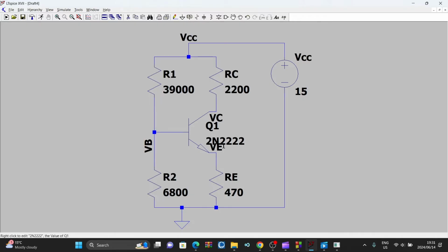Then when you minus, there's a voltage drop here, VCE. So how you can do that is, you can minus VC minus VE. That will give you a voltage drop across there. Yeah. Then this is our circuit for the DC biasing, it's ready.